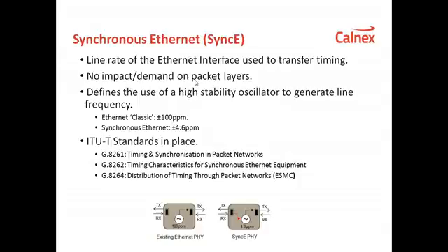And there are two fundamental differences between traditional or legacy Ethernet and synchronous Ethernet. The two differences are explained first of all at the bottom of this diagram. Legacy Ethernet physical devices, or PHY, at the interfaces have standalone oscillators. And this is a problem because remember, what we're trying to do is lock the incoming signal to the outgoing signal, and there is no such path in this device.